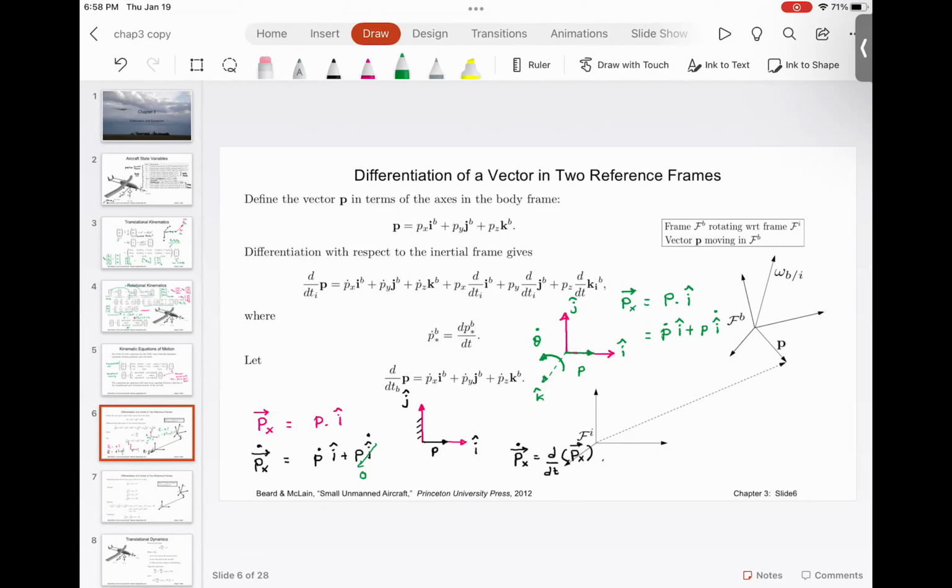But I'm going to give you a simple rule, which is called circle of vectors. And remember this. Can you see that this rotation is about K? Is this rotation or rotation rate positive or negative? Curl your fingers in the direction of rotation. Thumb is pointing towards positive K axis. So do you agree with me? Theta dot rotation is positive.